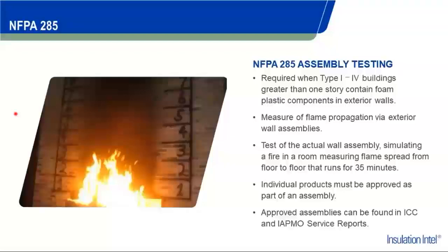And I simply always ask, who wants to take responsibility for that? So my suggestion is if you have an assembly that is approved, use the assembly. If you start mixing and matching or substituting in, you begin to play around with some unknowns, and then potentially could have a huge impact on the safety of a building.